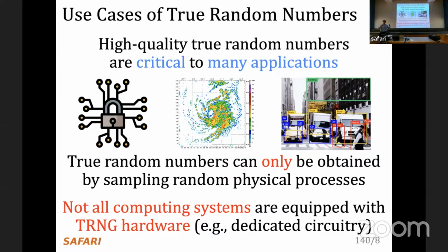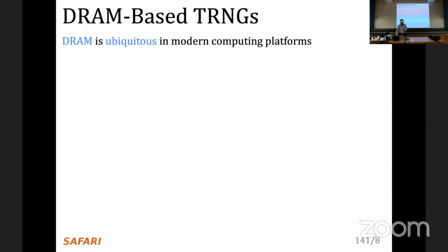Normally, you can have a pseudo-random number generator by using linear feedback shift registers and providing different seeds, but these are traceable. Meaning you can figure out the random numbers that you would get, assuming you know the seed, and you can discover the seed, etc. So true random number generation happens when you have a physical source of randomness that hopefully cannot be, let's say, hacked, if you will. It really generates true random numbers. Of course, if you talk about the theory of randomness, people always have some arguments about what's true random, what's not true random, but I'm not going to get into that.